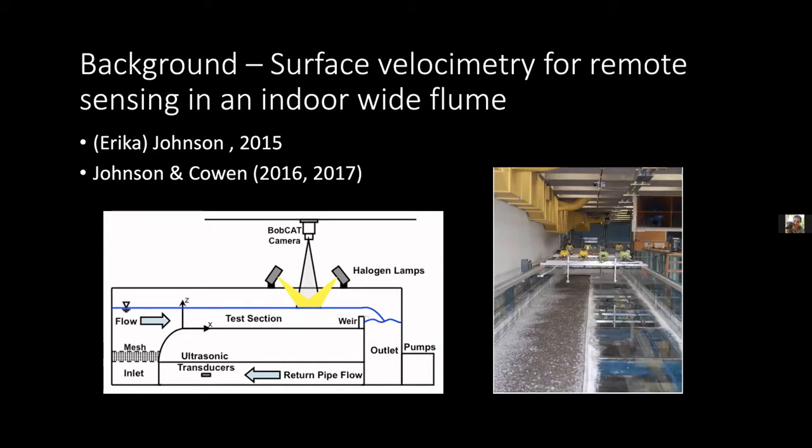So in her PhD work, she had a really nice wide indoor channel and was using surface PIV and some other techniques to see how you can predict the bathymetry when you are not doing in situ depth measurements, and then whether you can measure a volumetric discharge just from surface measurements alone.